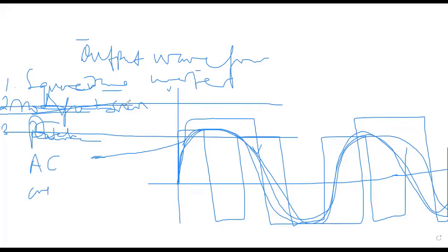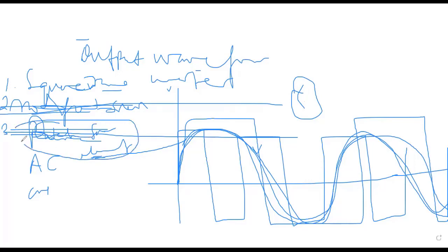If you use a modified sine wave to power some inductive loads, like maybe your standing fan, you may hear some uncomfortable sounds because it is not working with the equipment excellently. If you have sensitive devices like electronic devices that require a pure waveform, the pure sine wave would be the best for you to use. So I recommend a pure sine wave inverter for all your system installations.